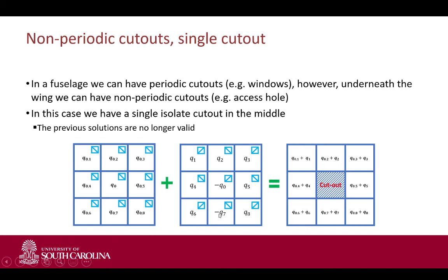Q7 should just be a plus, it should not be a minus, by the way. And then we can get our actual shear flows in the panel with the singular cutout. So it's just not repeated in neither X nor Y. So that's the approach that we take.